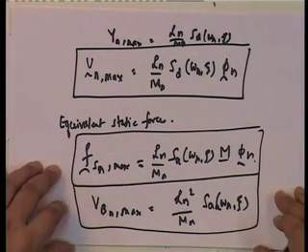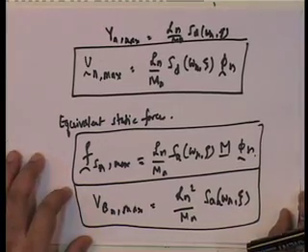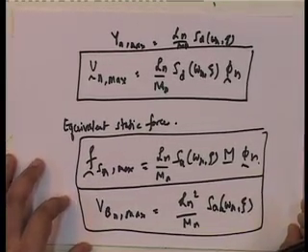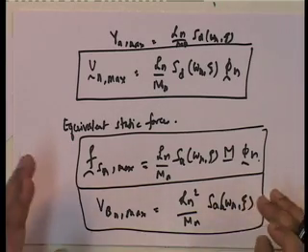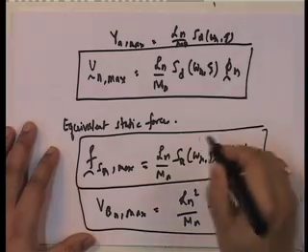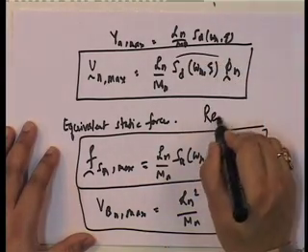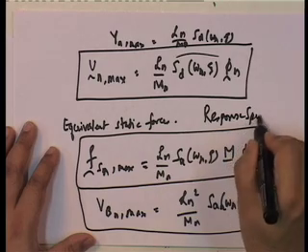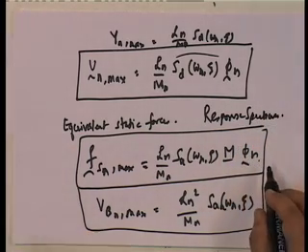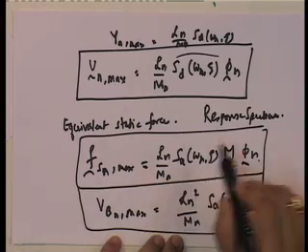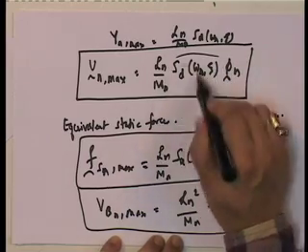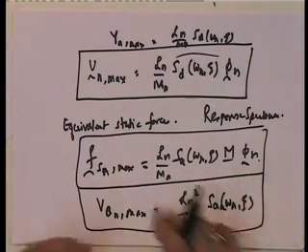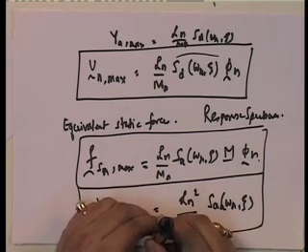The point that I wanted to make here is that we can get every displacement in each mode, the peak value, in terms of the response spectrum. The only thing is that for each mode, since it is omega n, xi, the values of Sd and Sa are different. You have to take that particular omega n and then read it off.